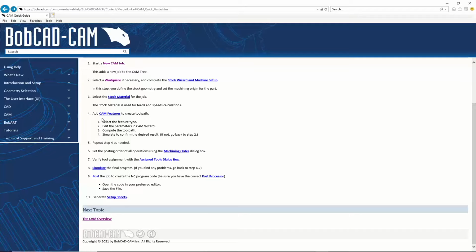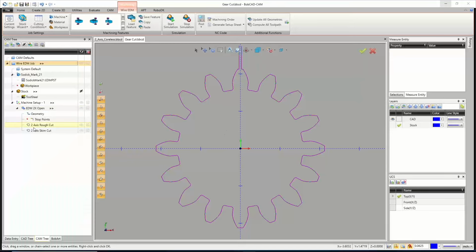Hold on one second. So with the setting as is, will it cut the outside or on the line? So Ken has just asked about that. So the setting as is right now, it will cut center line until I'm at the machine and I use my G41 and actually apply the offset. And then after the offset's applied, it should be to the inside of this cut. G41 should put us on the inside.